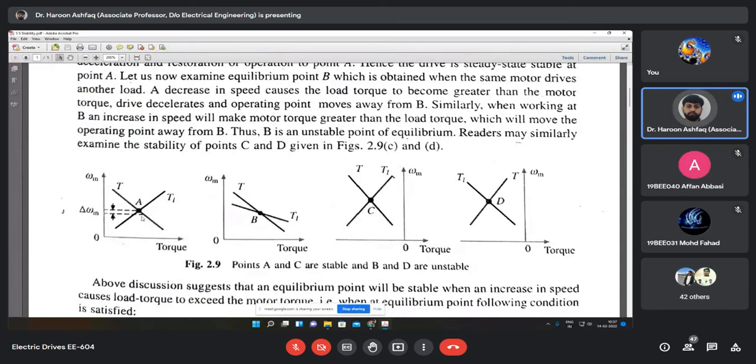That means if you have taken two characteristics and joined them, it does not mean that it is going to stick at that point. It may run away. For example, in synchronous motors, even if you put your system into synchronism, and you place so much load on the rotor, what will happen? The rotor will jam and the synchronism will be lost. So it does not mean that if you have made both characteristics meet somewhere, it is going to operate stably.